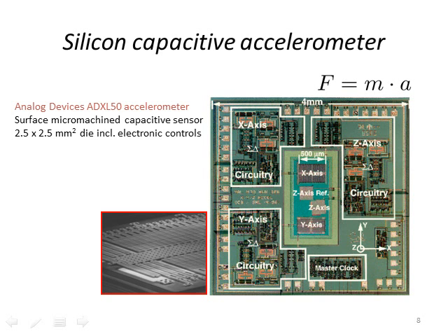So these miniaturized sensors are based on comb finger capacitors that move when mechanical structures move with changes in acceleration, etc. The bottom left-hand picture is one of these comb finger capacitors that has thousands of interconnected fingers to give really high overall capacitance overlap values. And amazingly, you can buy this accelerometer for a few euro.